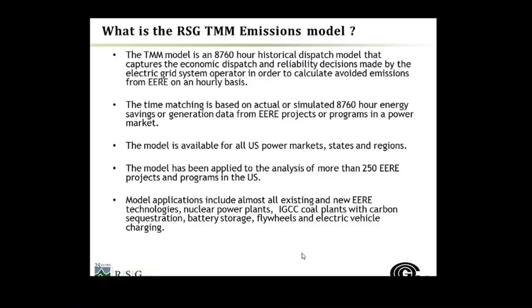So just to make that clear, for a wind project that you want to measure, you would get either an actual generation profile for the recent year of operation, or if the project is not yet built and you're deciding in advance whether to include it, you would go to the developer of the project and get the weather data, the wind speed data, and convert that into the hourly generation.